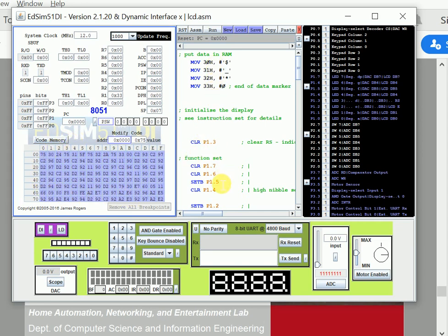So whatever code you write here and save will be saved in the code memory. Instead, the provision has been given. See, you can directly edit the code here, but it's not recommended because it's hexadecimal code and you won't be able to understand it. Instead, direct assembly language code can be entered here. And there is also a provision for entering embedded C code here. You know, the 8051 can be programmed in two ways, by embedded C code or with assembly language. Today we'll use an assembly language program, but embedded C code can also be assembled with this simulator.